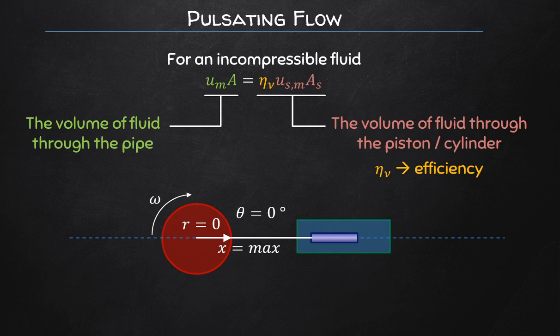So compressible flows, think about how they would react to this stop and start motion. Obviously a bit better. They have a bit of a dampening effect because they can be compressed. But nu is going to be much lower, because by the time your piston is to the far right and it's pushing pressurized fluid, the pressure is now alleviating before the piston then moves backwards. So there's a bit of an inefficiency going on here.